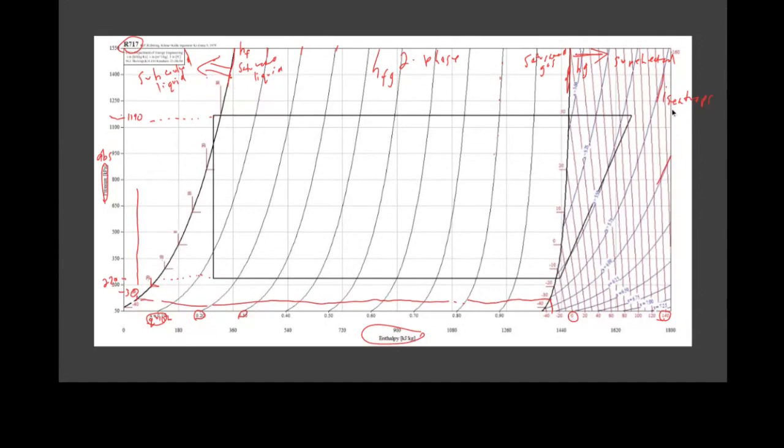And this is a very useful thing for us, very important for us, because if we have isentropic compression, first of all, we're compressing gas. We're not compressing liquid. We're not even compressing saturated gas. We are compressing superheated gas. And if we're compressing that gas, the compression process comes pretty close to being adiabatic. We could do calculations like you've done with steam plants and isentropic efficiencies and things like that.